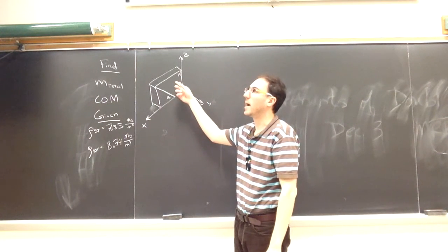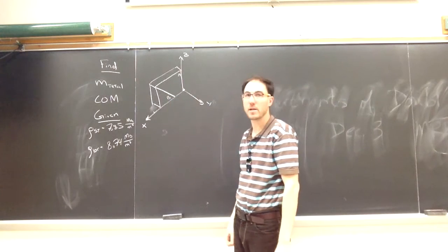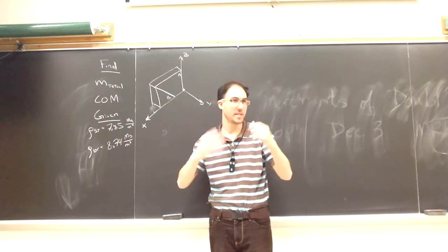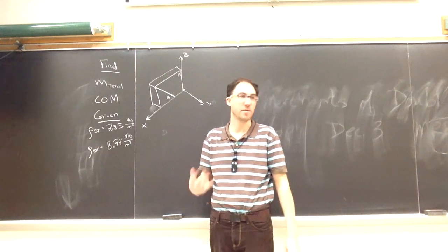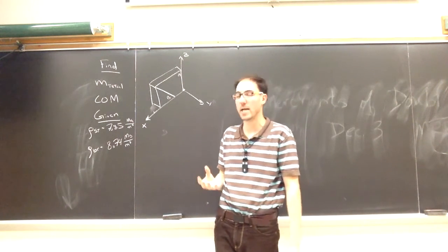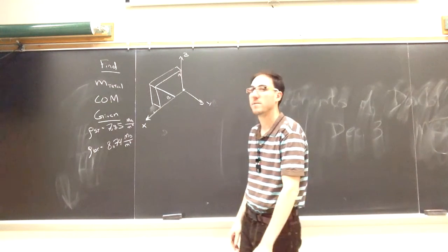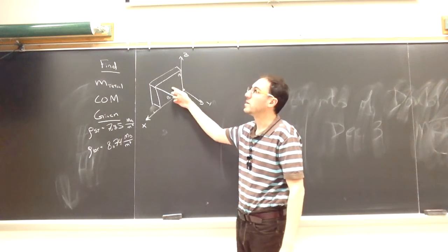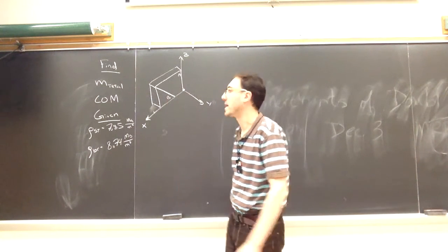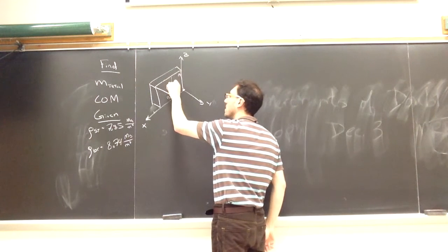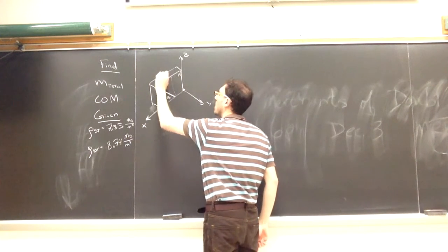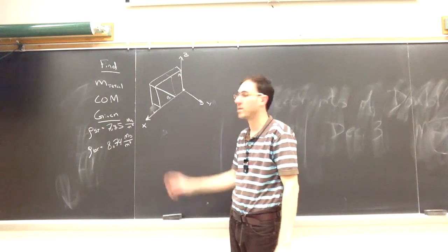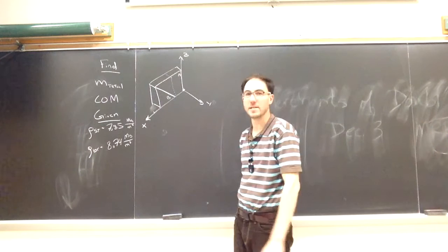So shape A, what we have here, is a trapezoid. We could treat it as such, but I think it's going to be easier, instead of worrying about how to find the area or the volume of a trapezoidal solid, to just have more simple shapes. So for this one, I'm going to break A up into a rectangular piece and a triangular piece. So A I'll actually make two shapes out of, and B is already a triangular solid. I'll just leave it as that.